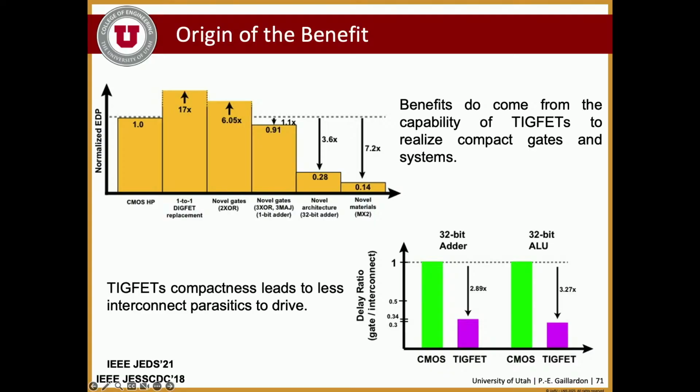But now you can start applying all the different tricks I showed you, right, at the circuit level. Now, if you implement novel gates with 2 input XORs, well, guess what? You reduce area, the overhead by 2. You also have the full adders. You can reduce that further. Now you start getting a gain. Because of the way you implement your gates and topologies, it becomes very cheap to use dual rail logic, for example. So you can also change the way you implement your architectures, and that gives you an additional gain.